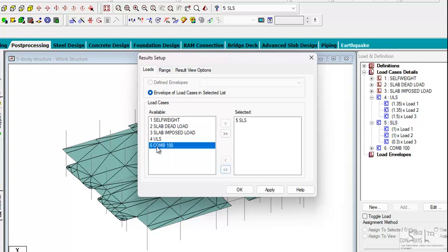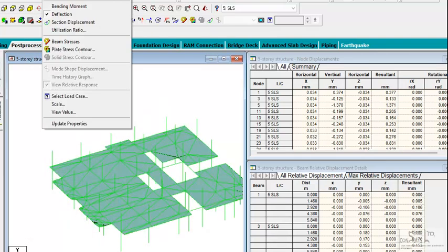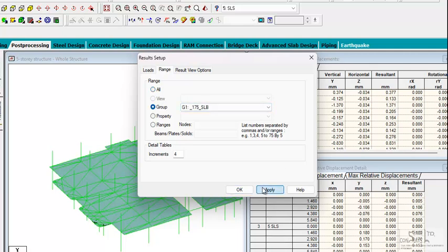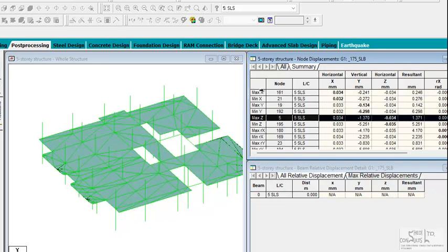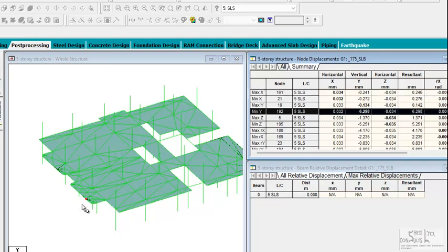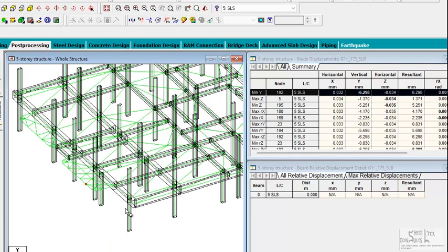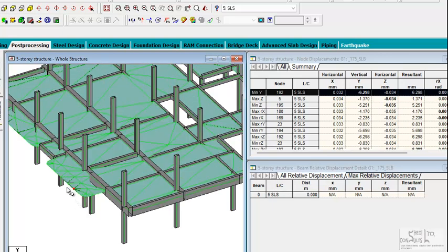Now, at the conclusion of analysis, something is interesting to note. This is a 175 millimeter thick slab. If we look at the maximum deflection on the slab, it is shown here. The maximum deflection of the slab is on the 2.614 meter cantilever, and this deflection is 6.298 millimeters.